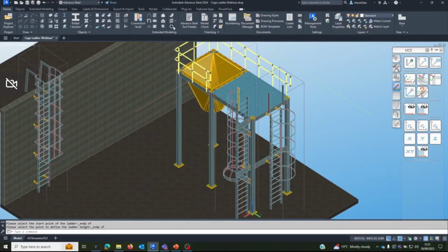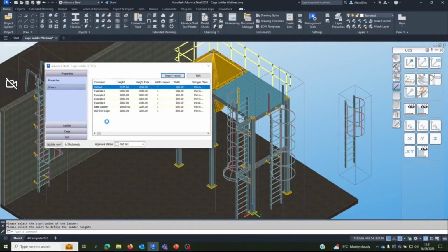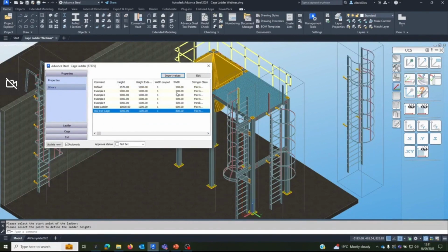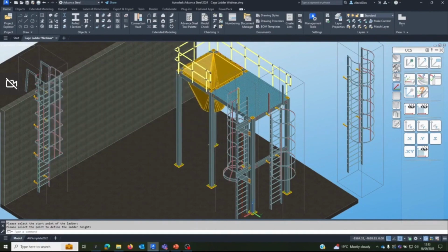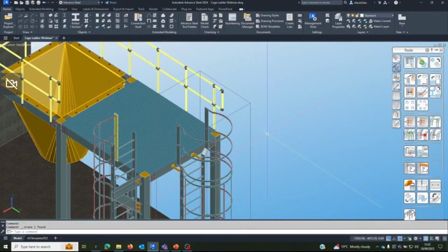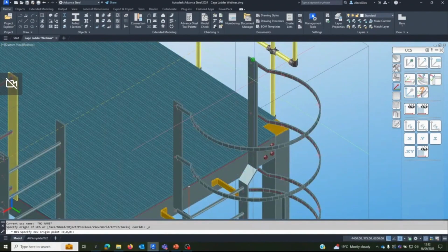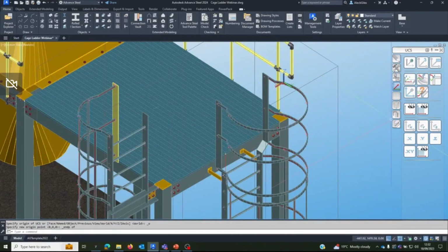Then I can do any other ladder nearby. And this time from the library I choose my exit cage configuration. That's all created for me, so I simply need to do that copy, those top three bands, or braces I should say, from the top of the stringer there to the top of the stringer here. And delete that temporary ladder now. Got my UCS. Top of the brace and extend the bands.